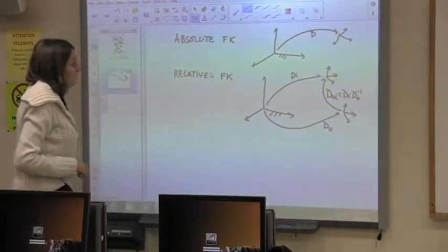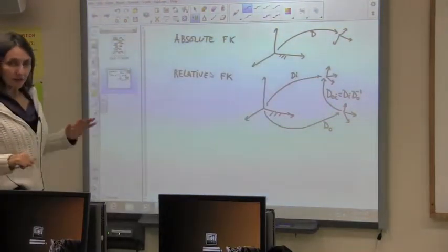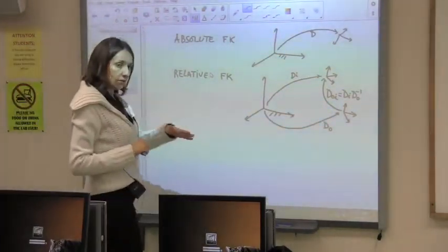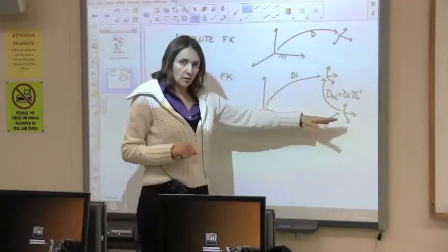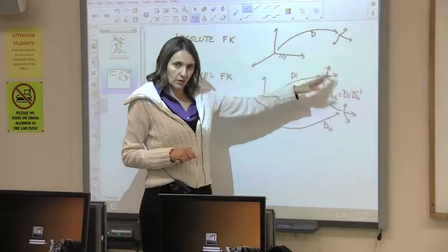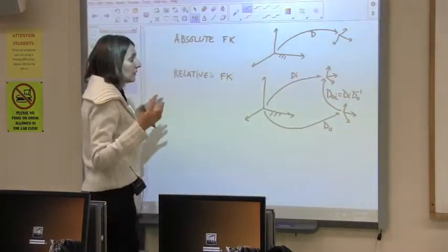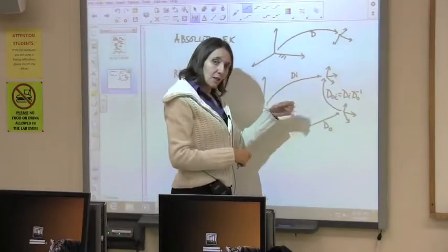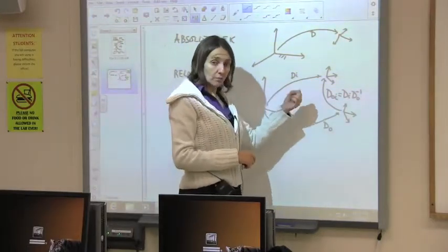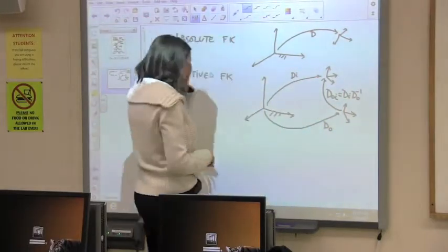So this is the forward kinematics that we will use, from a reference configuration to another one, not from the origin going through the chain, but assuming you already know your chain and move from there to another position. That has the advantage that it eliminates all the fixed parts. What you end up with is only the motion about each joint.